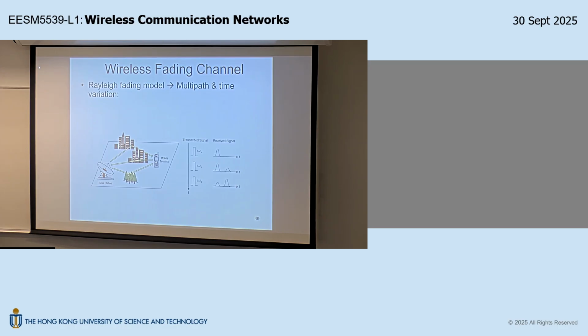So if you turn on that transmitter, imagine that this room will have some spots that receive high power, some spots that receive very low power, right? So high power spots correspond to the bright spots, where the path difference between these multipaths gives constructive superposition. The dark spots correspond to this fading region where destructive superposition happens, right? So the difference is just that the screen is one-dimensional, but in this space it becomes three-dimensional. So if you happen to stumble into a bright spot, then your receive power will be high. If you stumble into a dark spot, your receive power will be small, right?